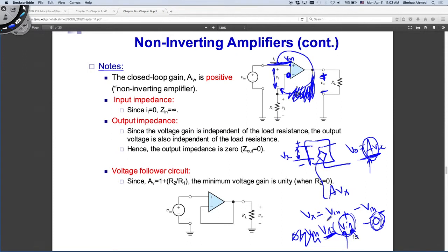So where do I feed it back? I feed it back to the negative terminal. If I feed it back to the negative terminal, it replaces this 0 with a large number. This large number, if I properly choose the value of the resistance, is equal to V input, and cancels out the effect of the open loop gain, and drives Vx to 0. If I drive Vx to 0, then I have the summing point constraint property that I want to see, right? That will help me analyze these circuits.